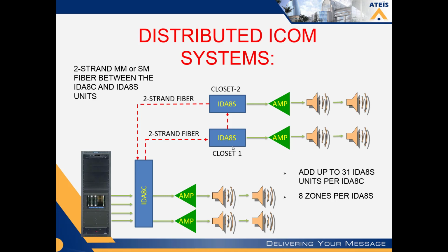And you can use fiber passive patch panels if you have a star pattern, depending on how your fiber backbone is laid out. So we can do distributed mode. Just remember, you're going to have an amplifier for your common area speakers in these distributed modes, out in these closets, the IDF closets or electrical closets. Chances are whatever system you're using is already going to have a booster or an external amplifier in that closet doing exactly this anyway. But you know, each school can be handled case by case and laid out in the best way that you need.